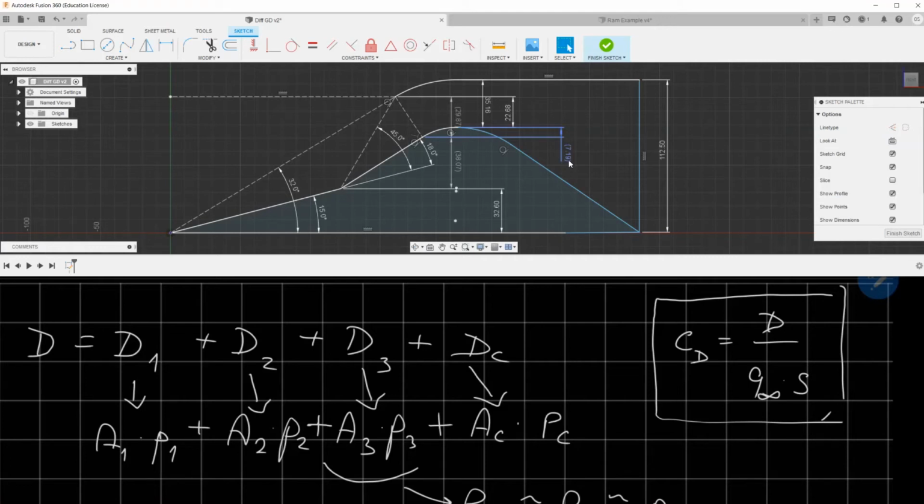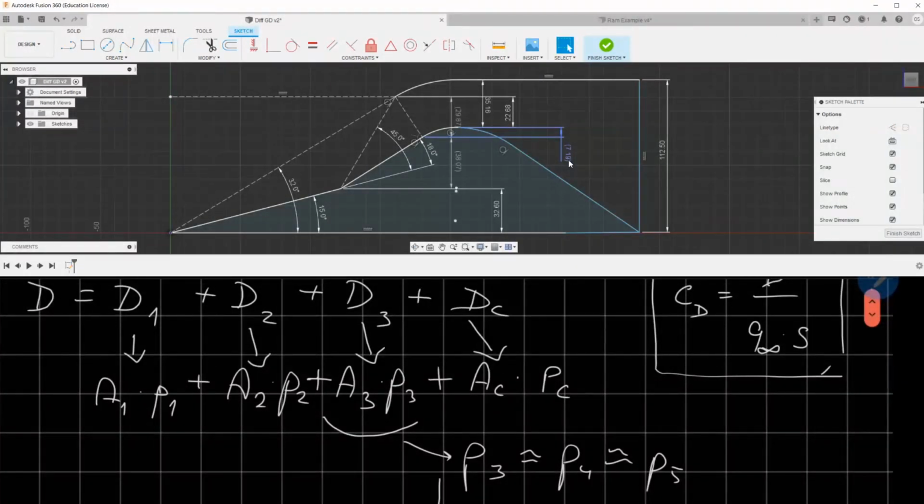That's it. That's simple. It's because the variation of Mach number is very small in the region at the exit of the diffuser. So after the normal shock wave and near this region, Mach number is practically constant. It means that pressure does not change, or variation of pressure is negligibly small. We can just assume constant value.